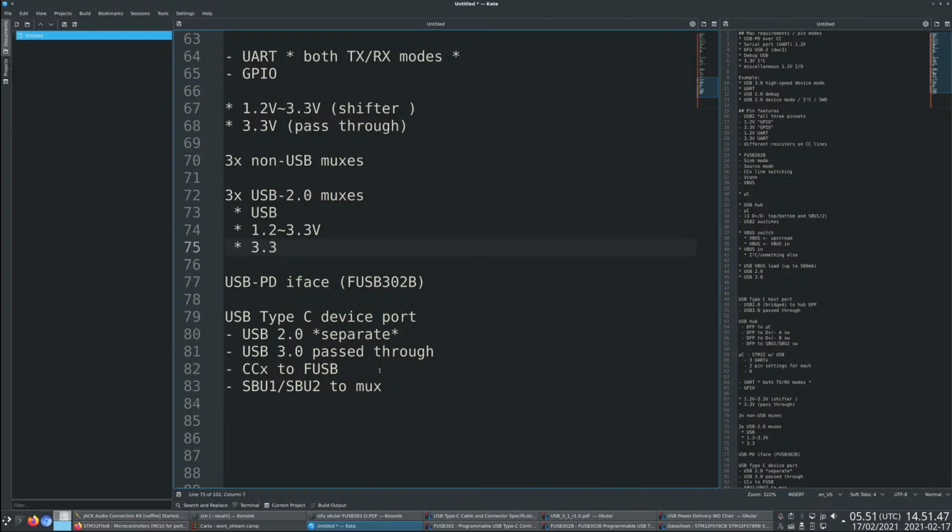In that case, basically, when you want to tee off for sniffing a Thunderbolt wire, you tee off the CC line and the SBU lines. No problem. That's just for sniffing purposes. I'm assuming you're going to be using some kind of external, either handmade or breakout pass-through board. You can buy Type C pass-through breakouts in China, and I'm sure they violate all the electrical specs for Thunderbolt, but you might even get away with it if you're lucky, especially if you don't solder around the actual pin headers on those sides, so it doesn't become an actual stub.